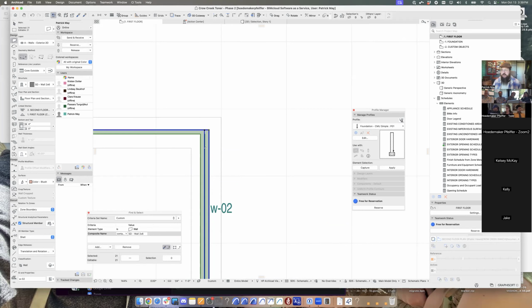And it updates those tags automatically. So it's actually pulling the element ID. I'm just using the composite to find those wall types, and then I'm unifying them to be the same element ID so that when I tag them, they get grouped that way. So we could, in theory, have one wall type that has a million different interior surfaces on it.